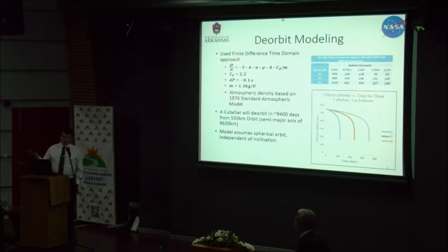But one thing to consider is if we successfully deploy the balloon, even if it gets a hole in it and leaks, it still has a significant amount of surface area that is not going to go away. It's not going to be as efficient, absolutely, but just the fact that we have a large balloon unfurled behind the CubeSat will significantly impact the orbital lifetime. Say we have a 45-year limit, and we need this system so that we can be under 25 years. Even if we design it to deorbit in 5 years, and then it fails completely, the addition of that extra material and surface area will bring us under the 25. That's something we would do a lot more analysis on if we make a flight unit. This whole campaign is going to give us all the information we need to make those calculations and make sure we stay in the safe margin.